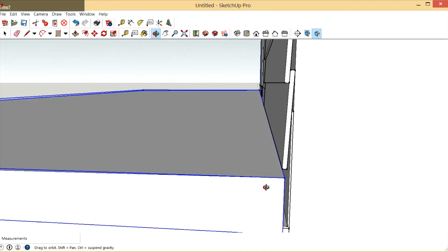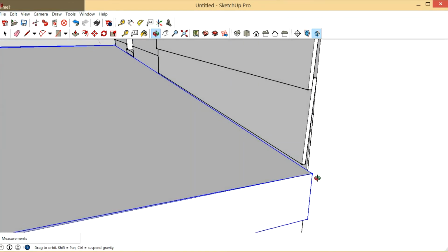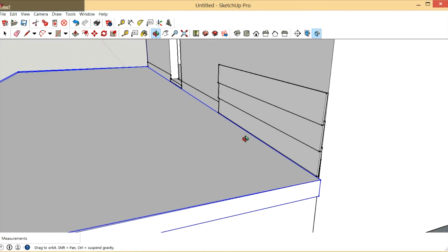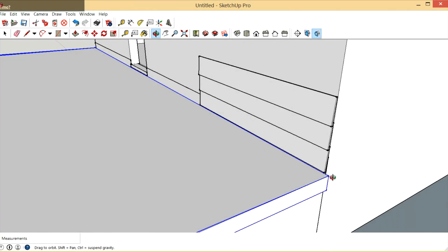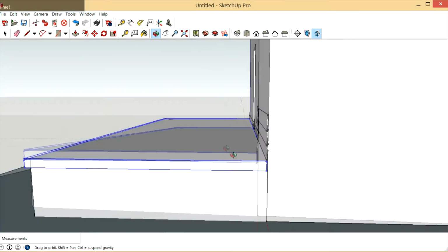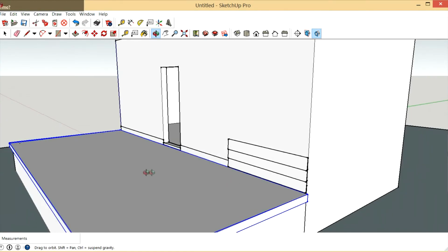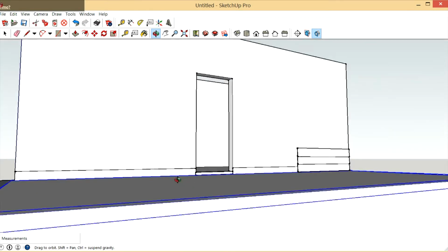It's a plastic cap, and before you put your siding and everything on, you pull that zip cap off, and it makes a little plastic channel for you to lay your caulk in all along there. Okay, so you've got caulk there, you've got sealant here, you've got flashing. You're going to be an artisan before you know it.